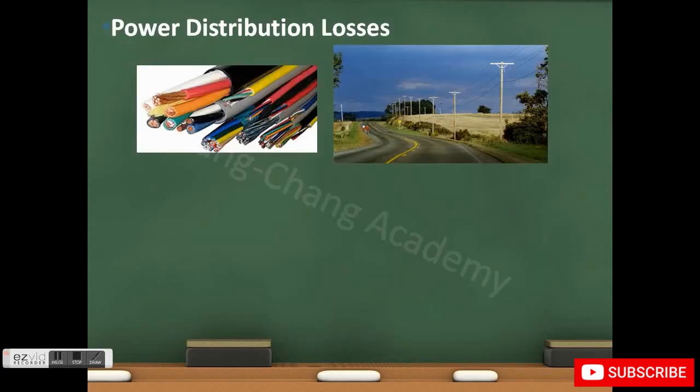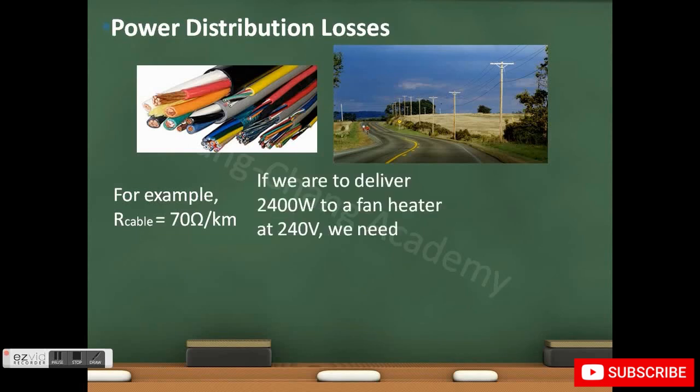Once the electricity is generated, we need to distribute it to the client, and a major power loss can result from the distribution. Consider this: if we use a cable which has a resistance of 70 ohms per kilometer, and we want to deliver 2400 watts of power at 240 volts to a client who is 100 km away. Since the power equals the current times the voltage, at 240 volts to deliver 2400 watts of power, we know that we need 10 amps of current.